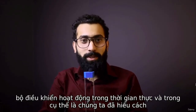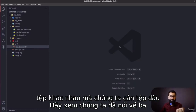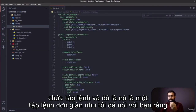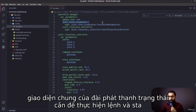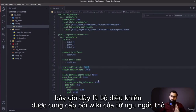Practically, we understood how controllers work in real time and in connection with Gazebo and ROS. Let's take a look at how things are going to work. We talked about 3 different files that we need. The first one was the config file, the script containing the controller, and that is it. It is a simple script, as I've told you, that just contains the joints it needs to actuate, the command and state interfaces, the joint state broadcaster, and the joint trajectory controller. The type of controller we will be dealing with is the joint trajectory controller. These are certain parameters provided by the wiki that we have set: publishing rate, action monitor rate, stop velocity tolerance and all that. This is provided by the wiki of ROS2 control. So this is the controller.